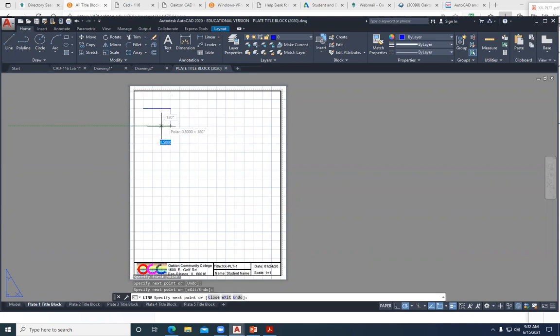And I'm clicking the left mouse as I go through, bringing this to the shapes that it wants to be. And then I'll hit escape. These green things are called O snaps, and they will fight with you because you might want to get it somewhere like over here, but the O snap might magnetize to the endpoint. And so you can turn that off right here, and then it will just go on the grid and the snap. And so then I could go and draw these other shapes as it's shown.